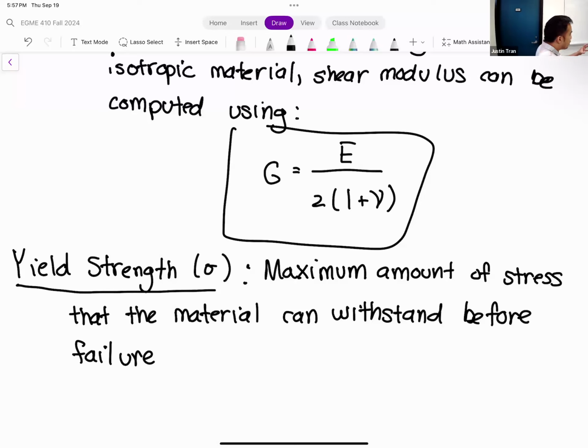The yield strength doesn't exactly belong to linear elasticity, but I wanted to mention it today just because we used it in activity 2. We're going to use it in activity 3 as well, and for one other activity when we simulate a car crash. So understanding the yield strength is important. One other thing I want to mention before I forget is that there are a lot of different stress metrics out there. Usually the one that we use to compare to yield strength is the equivalent stress.